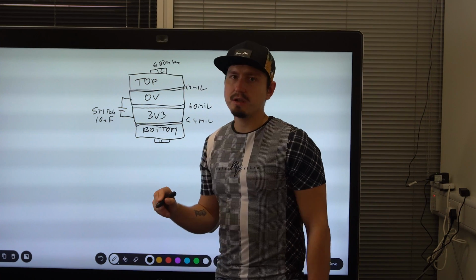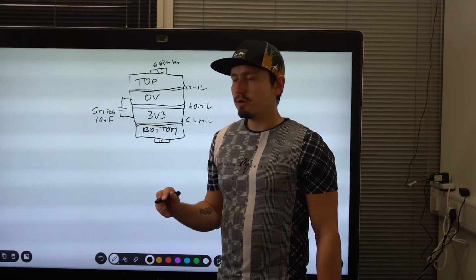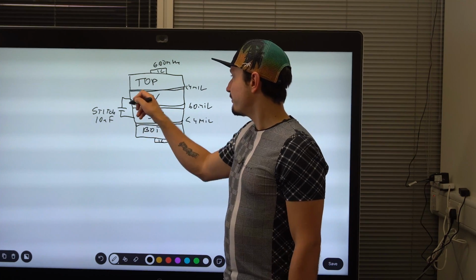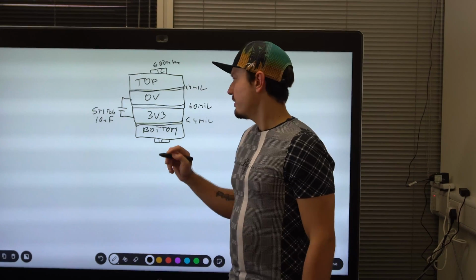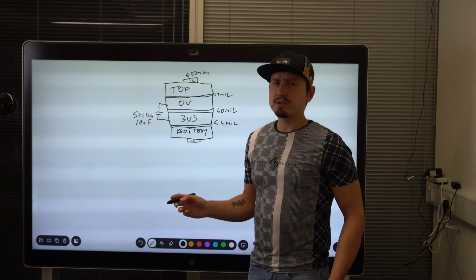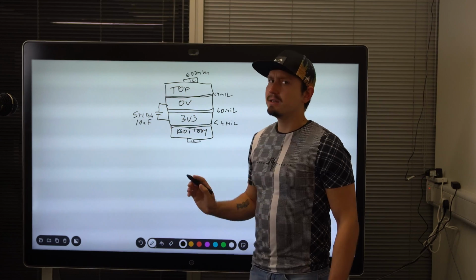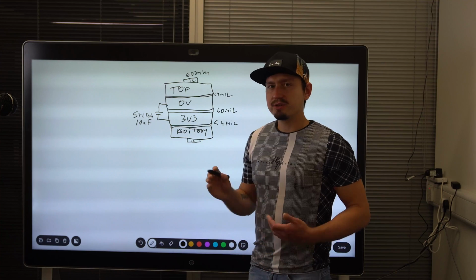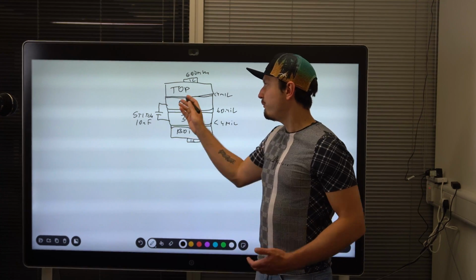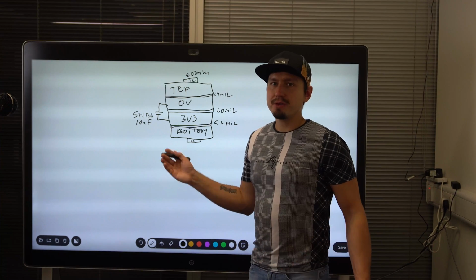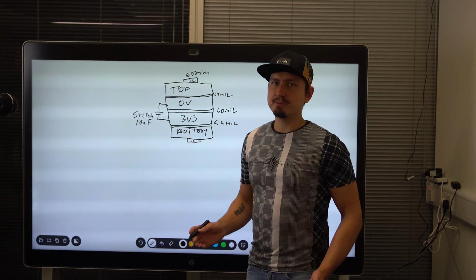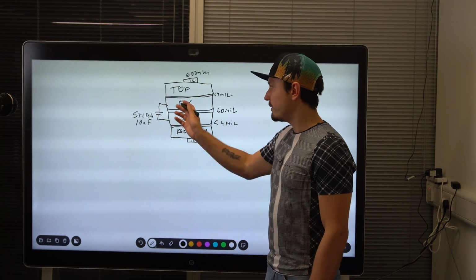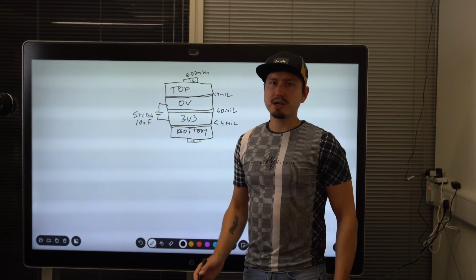It is typically a 10 nanofarad value. So what that does, it provides a direct path from one reference plane to another reference plane for the return current. And this is very important because it helps me to direct the current in the way I want it to go, and without this cap the return current will kind of be lost and it will find its path back some other way, but it will be completely unpredictable and it will screw up the performance of my PCB, so I don't want that. I will add this cap to make sure I know exactly where the current flows.